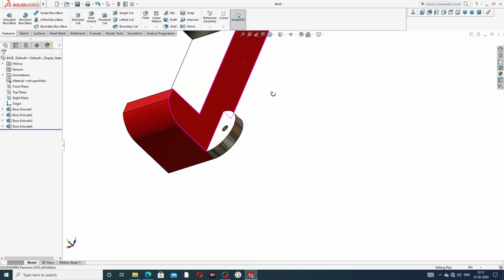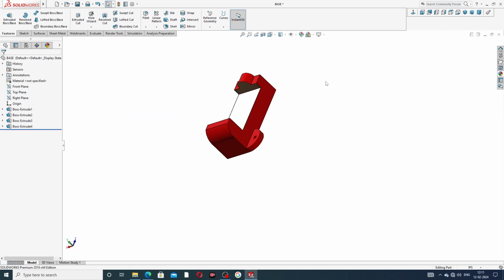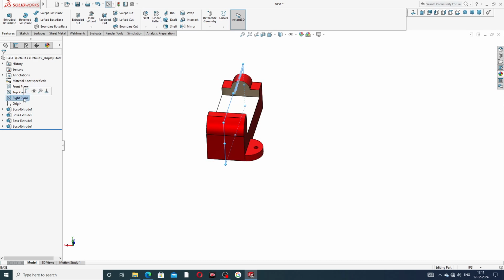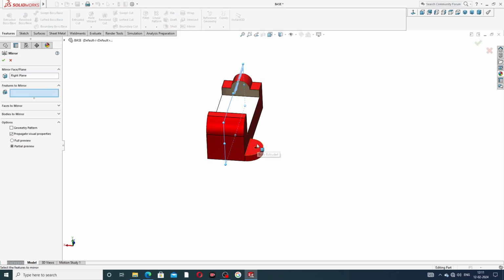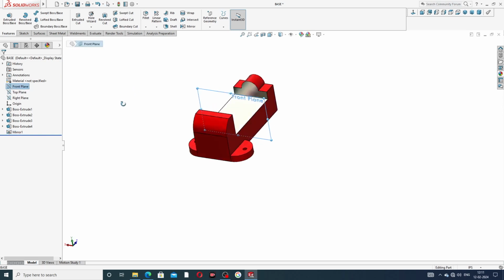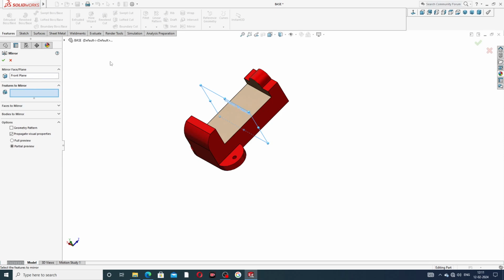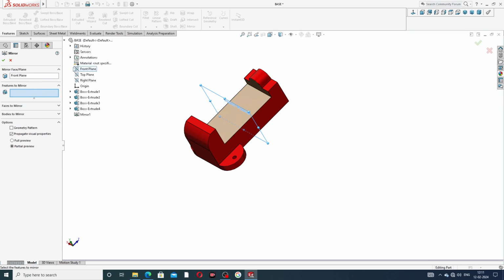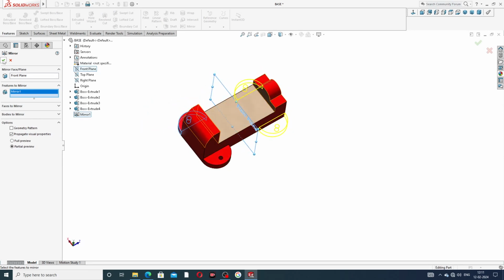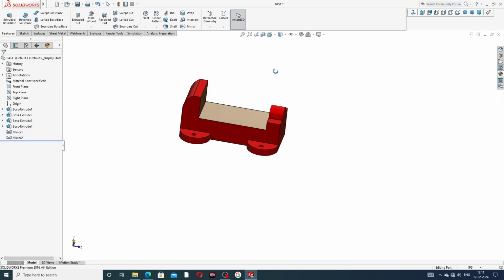Okay, and select this extrude and going to this color, and painted is perfect. Okay, and guys, all points are mirrored. Going to this, select a plane, the right plane is better, and X mirror, and going to this, it is mirrored here. And next is also mirrored here. Select the front plane, that is better, and mirror. Select both parts, and mirror them one time here. Okay, all is perfect and correct.